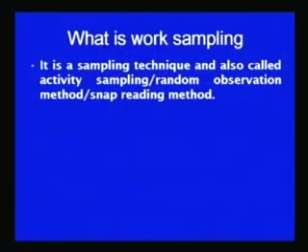Work sampling is significantly different from the time study technique, in which observation of the operator is directly carried out by the time study man with the help of a stopwatch. A stopwatch is used to quantify the time being taken by a worker for carrying out the job, and the time study man also judges his performance from his own concept of the standard performance. So, here the judging of the operator's performance from his own concept becomes significantly subjective and a matter of criticism.